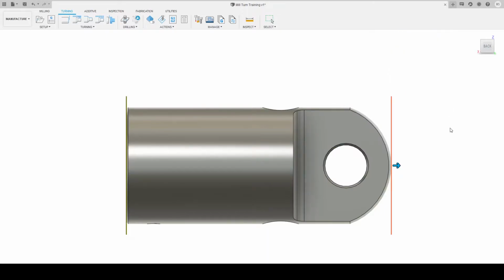If we don't want that, we can manipulate our handles and drag them, or we can go with any of these. We can go model back, we can go the chuck front, or we can go selection. We can go selection and select a point, and then we have an offset of 18, so we can go 0, and then it will be exactly where we selected. If we select another point, we can select this point, not a problem. But for today, we will go model front.